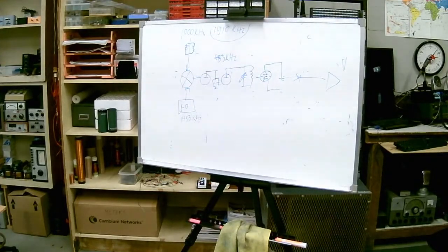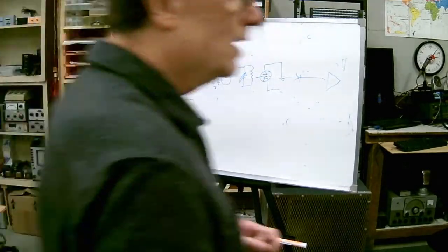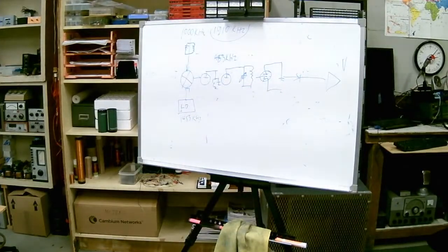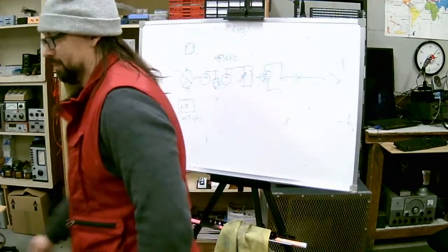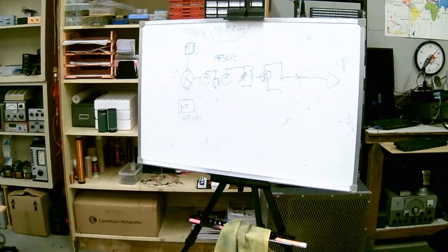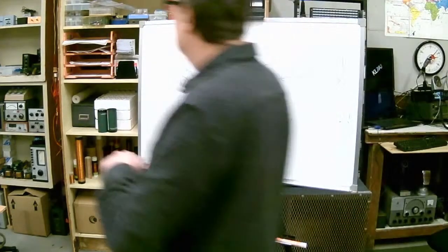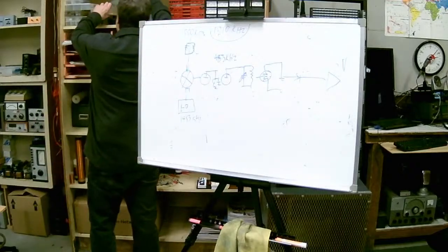These front ends had two capacitors. One was for the local oscillator, and one was for the selective stage ahead of the local oscillator. So that would take care of that. Anyway, that's a very typical front end capacitor.